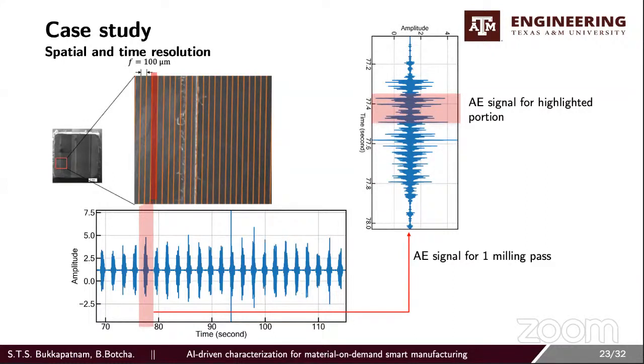Assume you are machining with a 5 micron depth of cut and then 2 microns. If you decrease it, the surface roughness will obviously go down. Now you take a burst signal for acoustic emission and convert it with the FFT analyzer. In that circumstance, will your signal move towards the datum, or to the left side, or higher or lower?